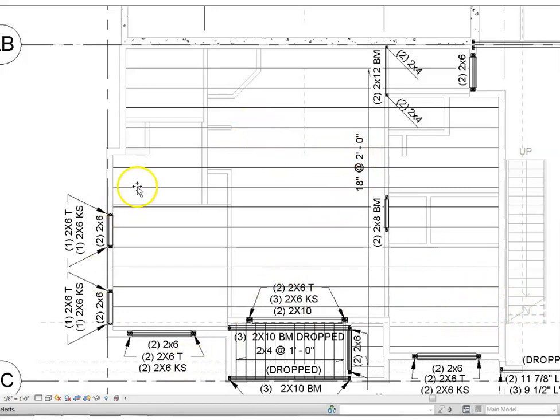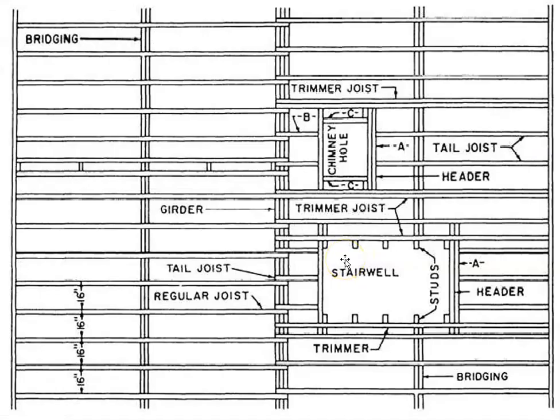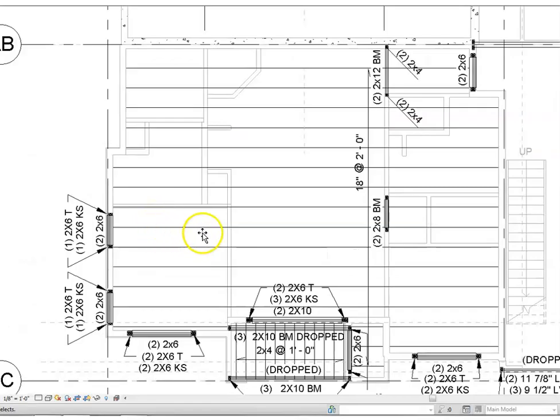So I can't see a lot of this here. I see foundation wall here. So these single lines, these are the joists. And yeah, so they're never depicted in construction documents as double lines. They're single lines. And we are probably, I'm not exactly sure what level we are on, but here we are pointing out that there are headers above windows. So it's telling us exactly what the sizes of those are and how many there are.